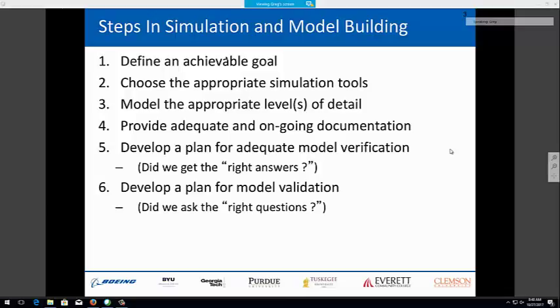If you're keeping notes, you should put a star next to step F. People are enamored with beautiful pictures. Sometimes those beautiful pictures don't make any physical sense. But man, if you can throw a beautiful picture of a contour plot of a displacement on a PowerPoint presentation that you might have due in just a few short weeks and it doesn't make any sense, that's a problem, right? So when you display those beautiful pictures, you have to actually figure out whether the results make any sense. Okay. A few comments and then we'll shift over to ANSYS.